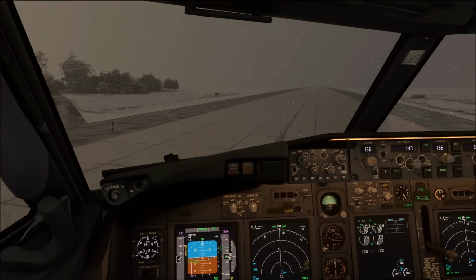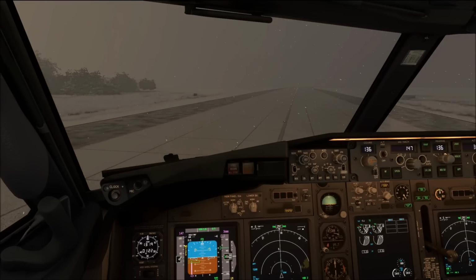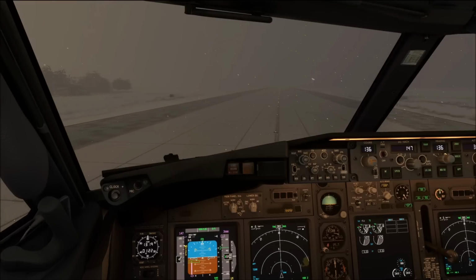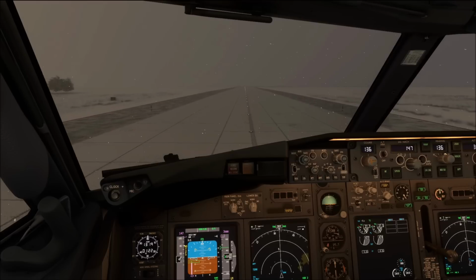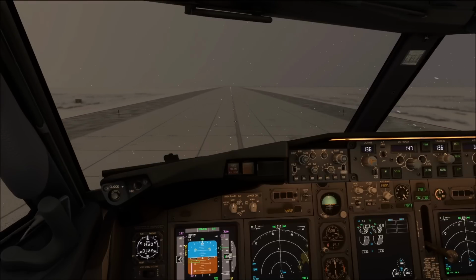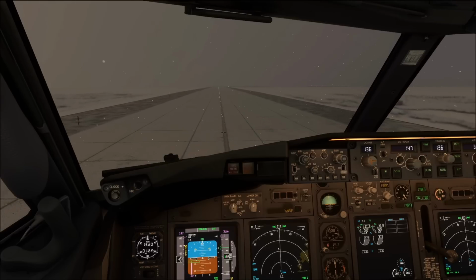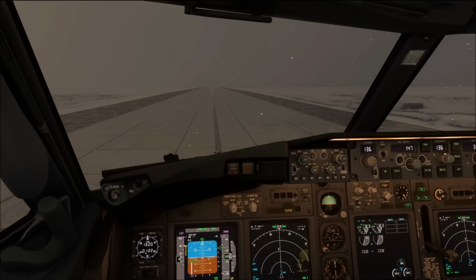While the crew was rolling all the way to the end, they reduced the speed to approximately 30 knots. Then when they approached the taxiway to vacate the runway at the end, they tried to slow the airplane down any further. However, they had already stowed their thrust reversers. They applied the wheel brakes and they simply did nothing.